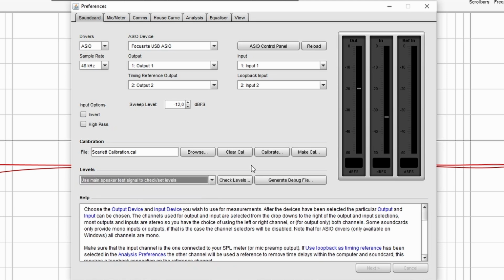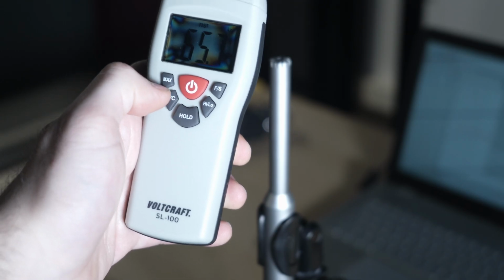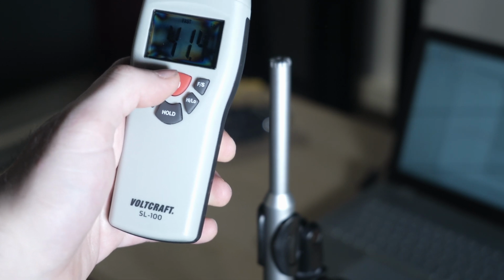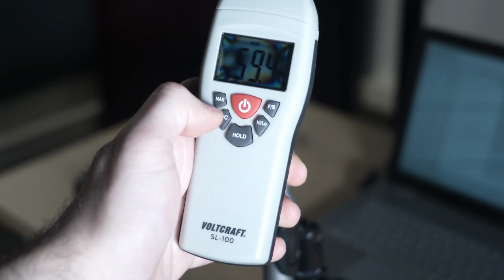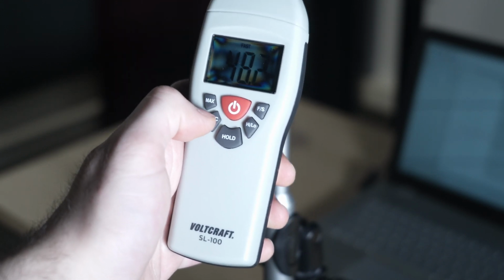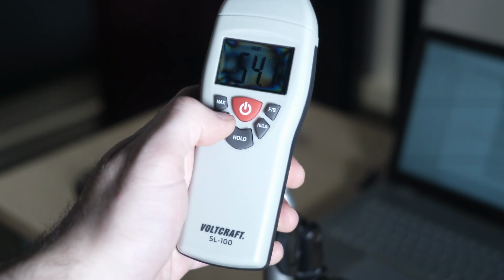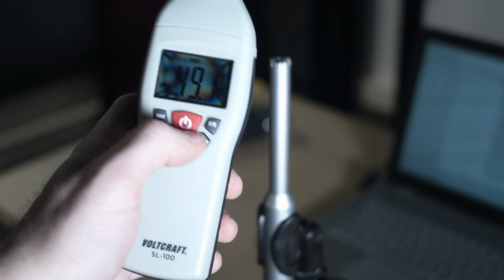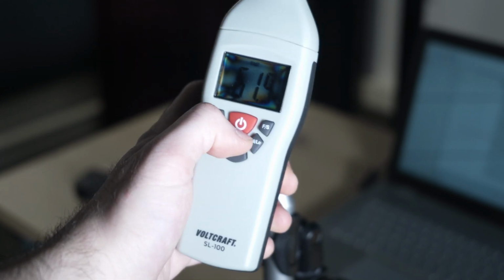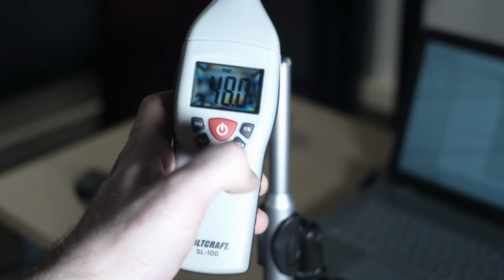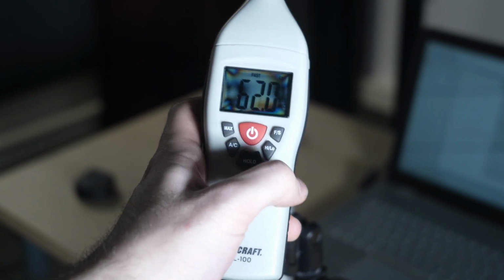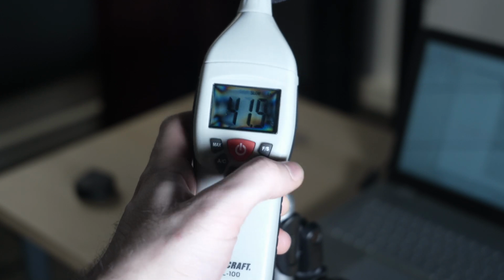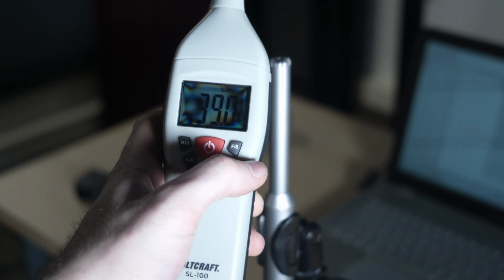Yeah, now I need to turn on my speakers and I've got a decibel meter right here. So a sound pressure level meter, but you can also use a phone app. It's not that important, it's just to compare the different measurements, because you don't want to change your levels if you're comparing stuff. So keep that in mind. Set your levels once and then don't touch them again. But what I want to do is change the curve to dBC. I hope you can see that on the camera, but so it measures an average signal. And I'm also going to change the speed from fast to slow.